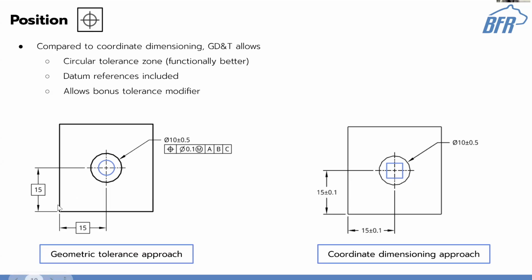It's got no associated tolerance with it unless you're looking at this box here, right? So this is just reference. When you're doing GD&T, it doesn't actually matter what those say. That's just for a human to interpret or read out how far away it's supposed to be. But this will always take the actual true position.